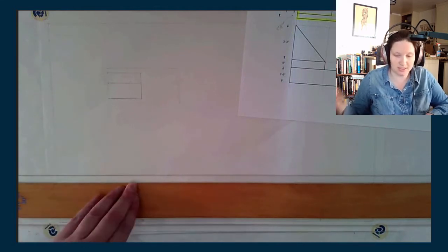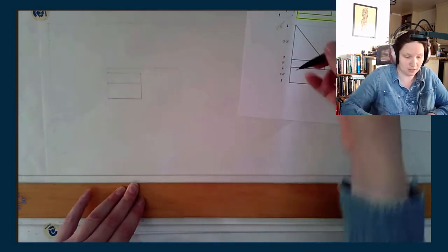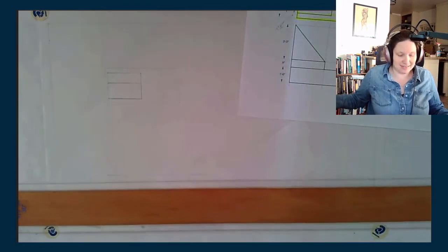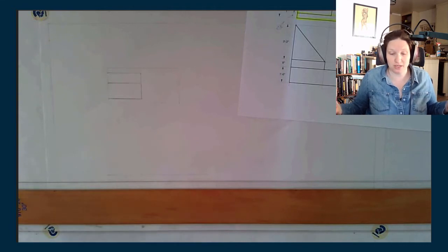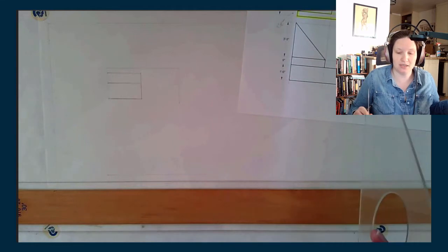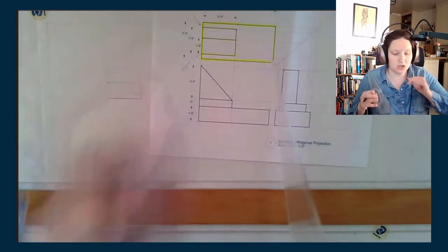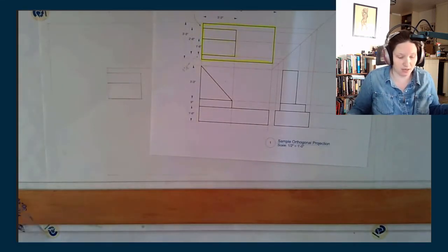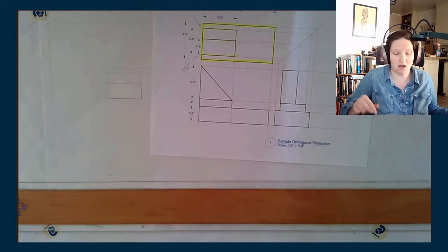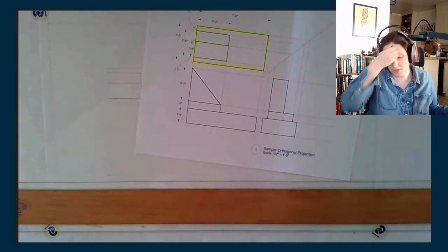And that's where I'm gonna place the baseline for this piece, okay? I'm gonna just very lightly draft that in. Now, instead of measuring, because measuring is a pain, I'm going to just bring down the existing lines, right? So instead of measuring 7 foot 0 inches again, 3 foot 3 inches again, I'm just going to pull down the lines that we have in an existing way. And these are the red lines on the diagram that we have, okay?